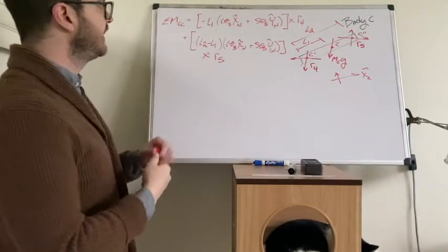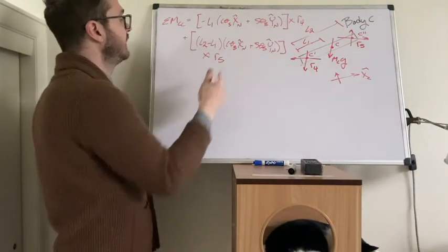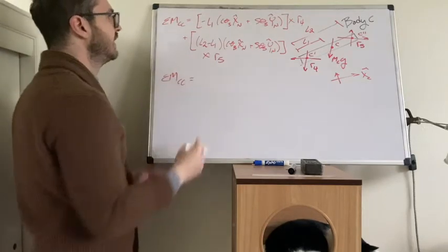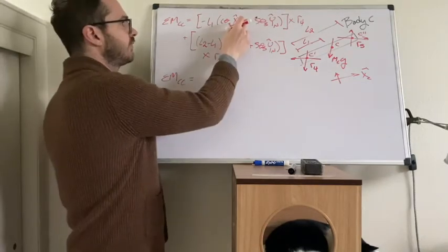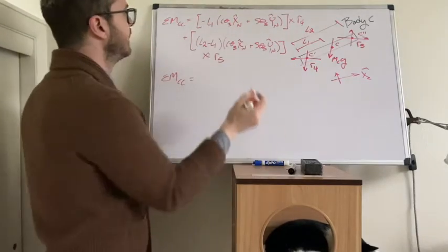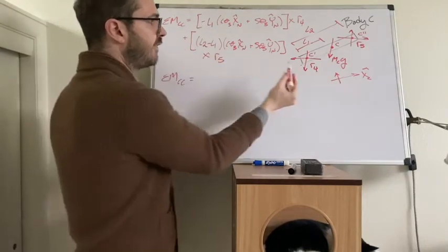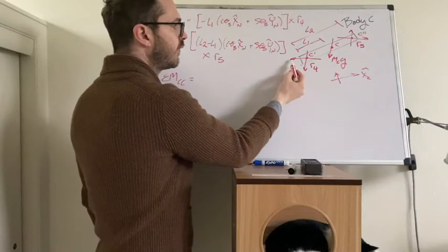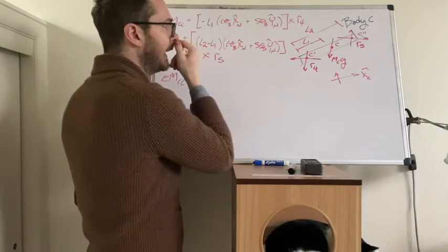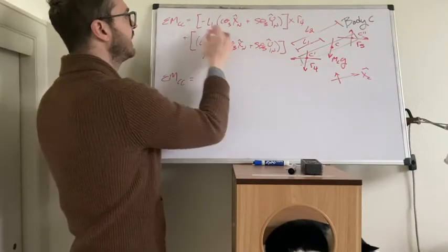So in each of these, we're going to have x cross the z term, x cross y. Sum of moments, C about C. If we do the x cross y terms, we're going to get positive z. Now, for this one, there's a negative in front. And on the R4, look at your notes, the R4 is negative in the X and negative in the Y. So we're going to take this X and cross it against that Y. It's negative here, it's negative here.